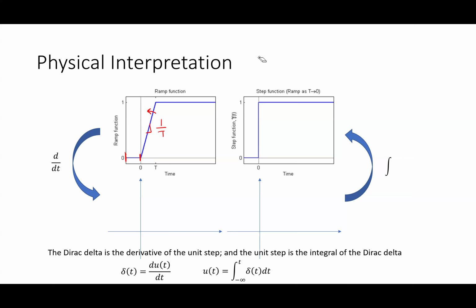What would you say is the derivative? So if you were in calculus and you were asked to define the derivative at that point where there's a rapid change in the function, what would you say the derivative is there? There's no derivative, is there? There is. All right. You said it was undefined, but in the context of signals, we usually try to give ourselves some tools to be able to think about it. And so what we say is that it's actually the impulse function.